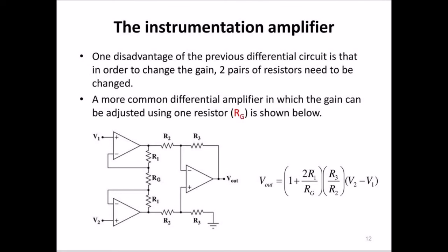Whenever there is a necessity of connecting a differential amplifier, and the system has to be made reliable and the output accurate, then we can connect this instrumentation amplifier by replacing the differential amplifier, if there is a dual input. If there is a single input, then the differential amplifier is enough. I hope this session was useful and that you clearly understood the instrumentation amplifier. In the next class we will discuss the chopper amplifier. Thank you.